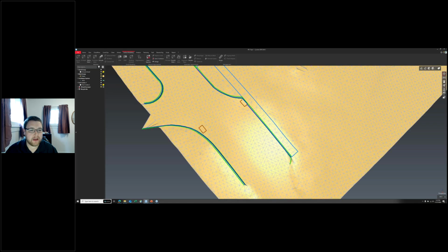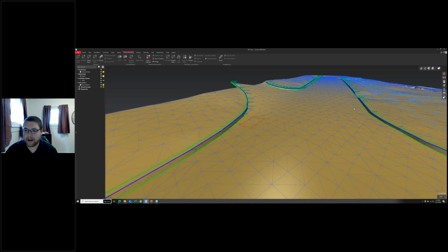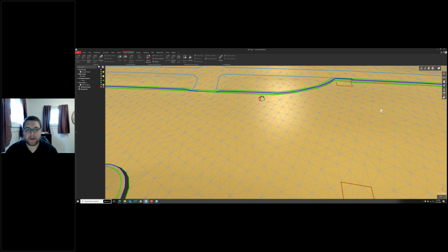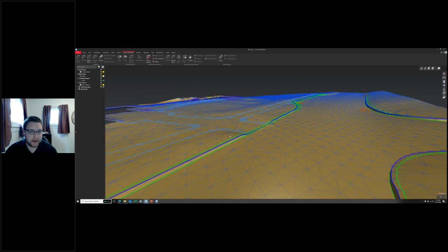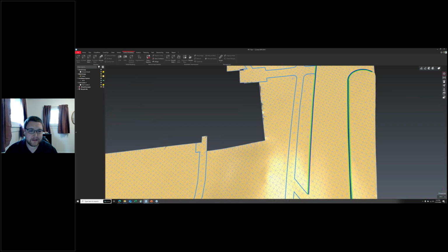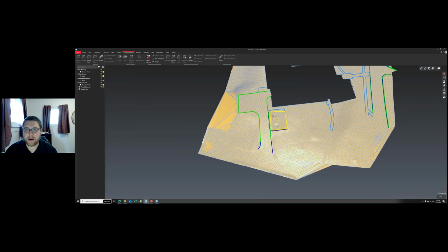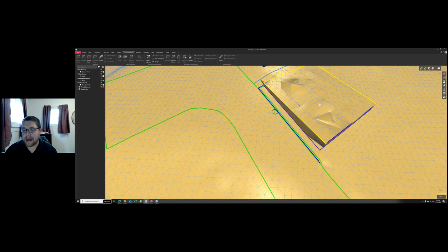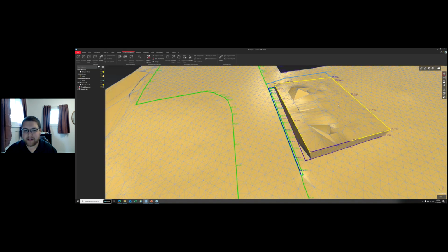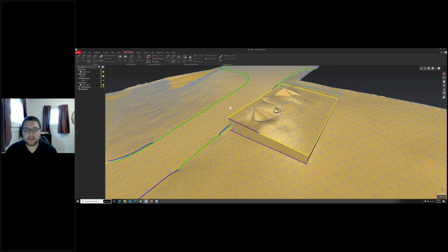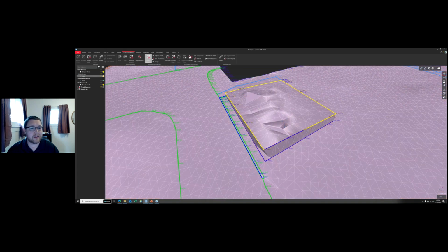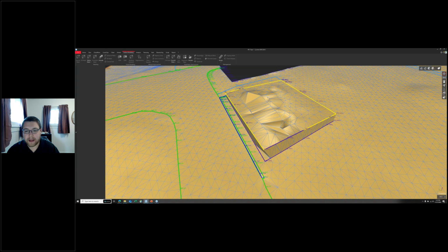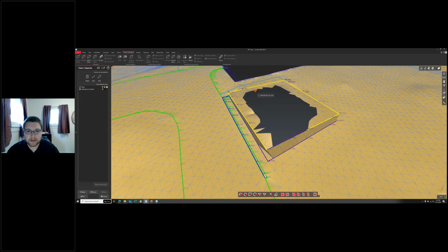So now we have a nice surface. We have our lines in, we have our curbs in, we have the nice curb cut there with it. Everything's getting utilized. I'm going to come back over here. I talked about this concrete pad. The triangles are a mess in here. I could easily clean this up using the clean and separate tool, removing these triangles and deleting them.